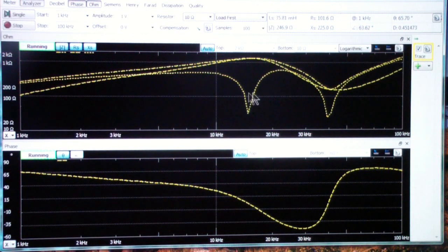And so these tremendous changes in impedance get reflected back through the feedback network into the input. And that's one of the reasons why hi-fi tube amplifiers would often oscillate at higher frequencies. Sometimes, in this case, this one might oscillate around 15 kilohertz, where this resonant point is, or around 36 kilohertz, where this resonant point is. Now, with better transformers, these resonances move out further and further, but they're still there.